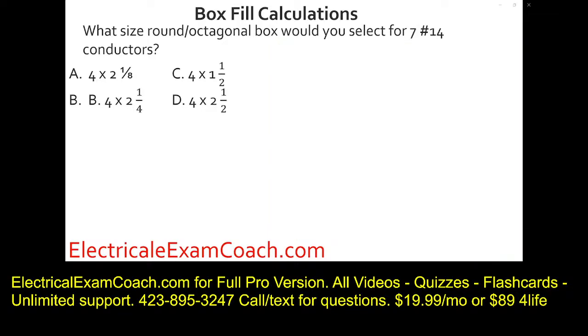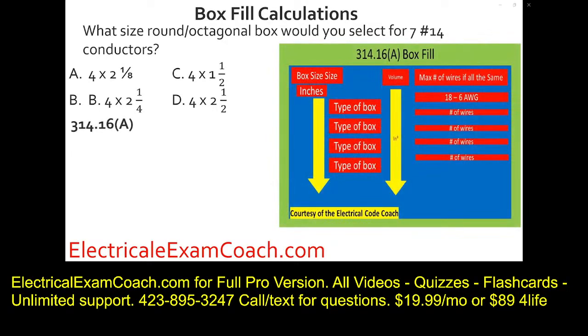What size round octagonal box would you select for 7 14-gauge conductors? We're going to head to table 314.16a.